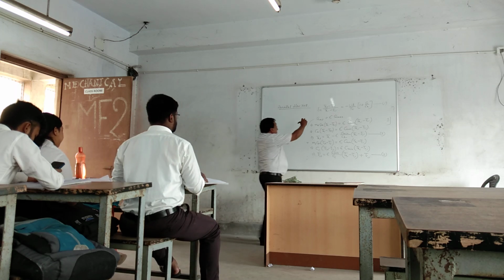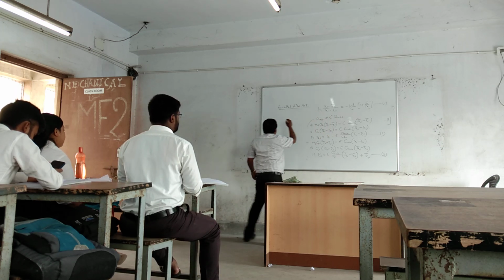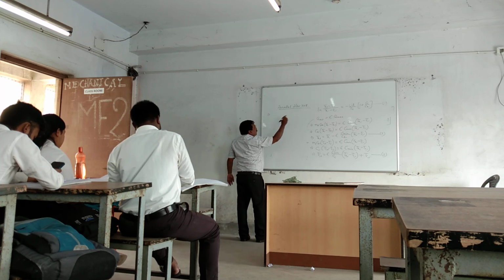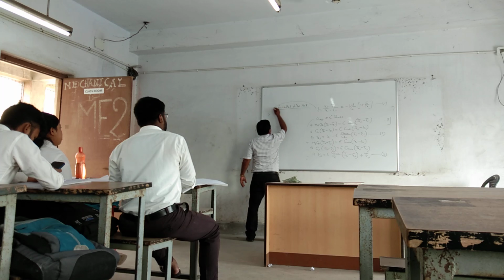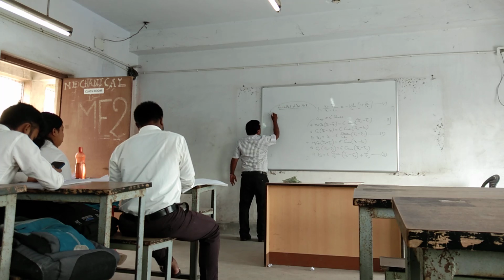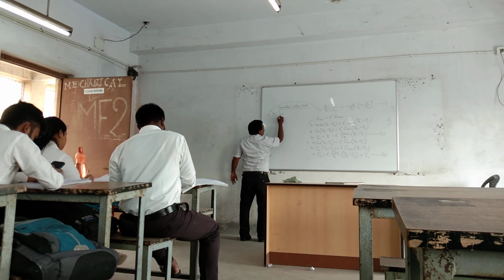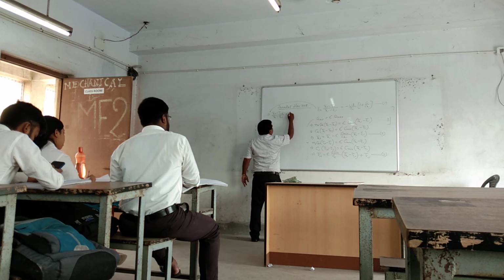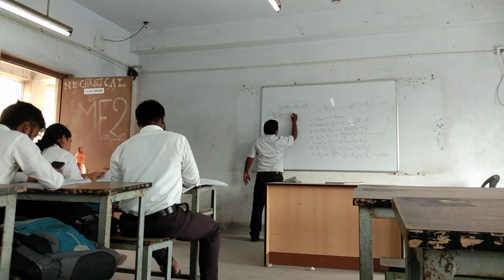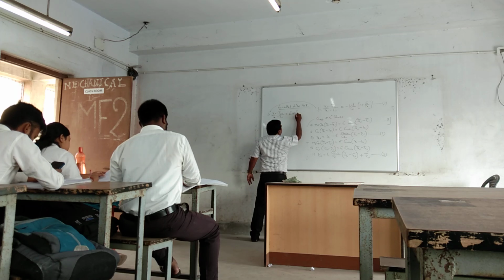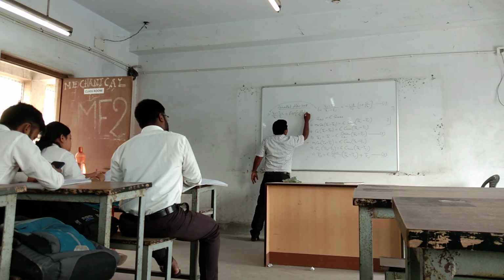You can write it using the logarithm sign, or from here we are getting (THO minus TCO) by (THI minus TCI) is equal to exponential minus UA by CC into (1 plus CC by CH).